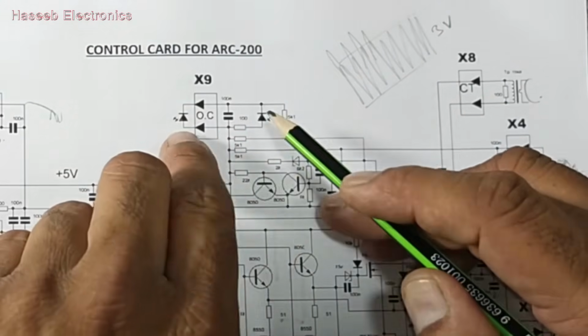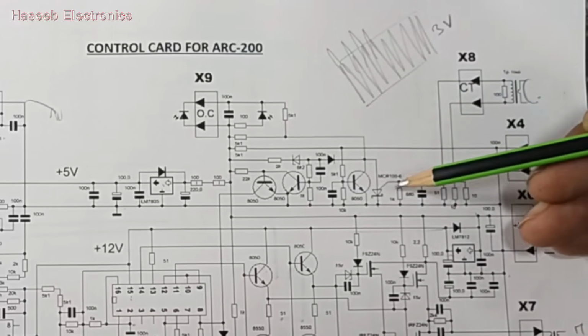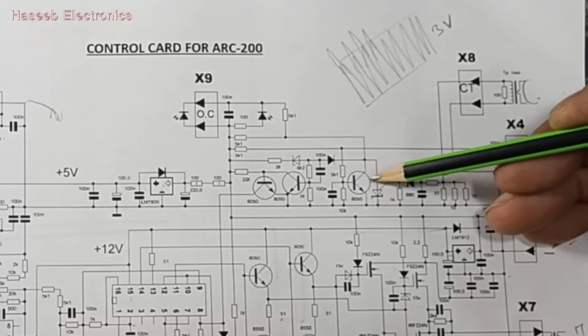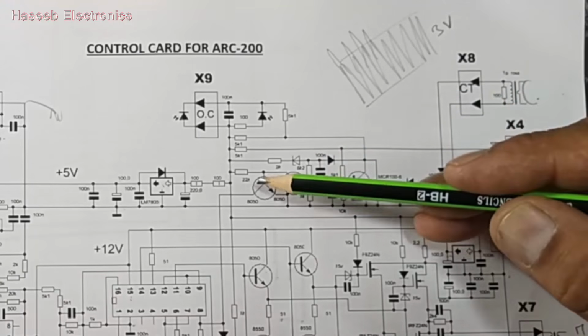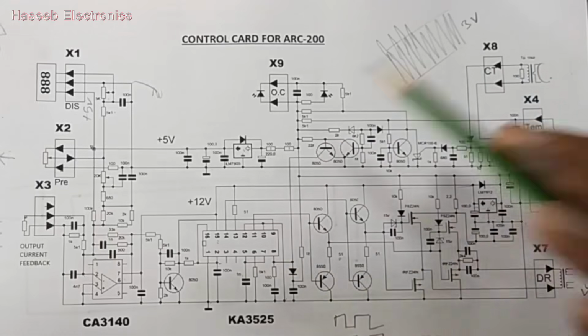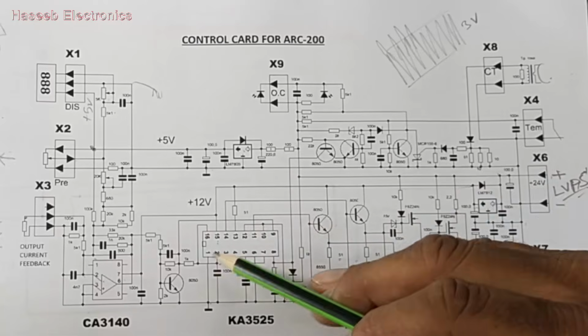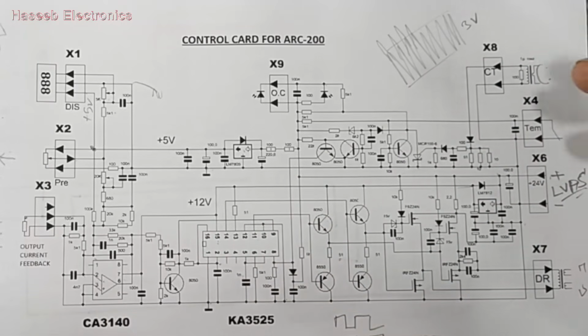That is in the front panel, this is on the card. So this LED will turn on. Now what will happen? This ground level will also pass to this transistor, and this transistor will switch and this will turn off this IC, because pin number 8, that is soft start. So this IC will turn off. Why? Because there is an overcurrent in the primary section.